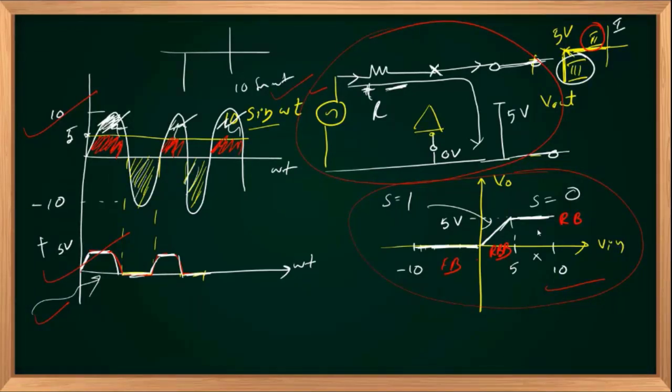We are opening the diode first, then we are identifying the different modes, then we are replacing the diode accordingly, either short, open, or with a voltage source. You should be careful while drawing the voltage source. Cathode is positive, then anode with a VZ value. VZ is the reverse breakdown voltage, VBR or VZ. So this is called a shunt clipper because the diode was present in parallel with output, and you have two different slopes, S equal to 0 here and here, and S equal to 1 in the linear region.